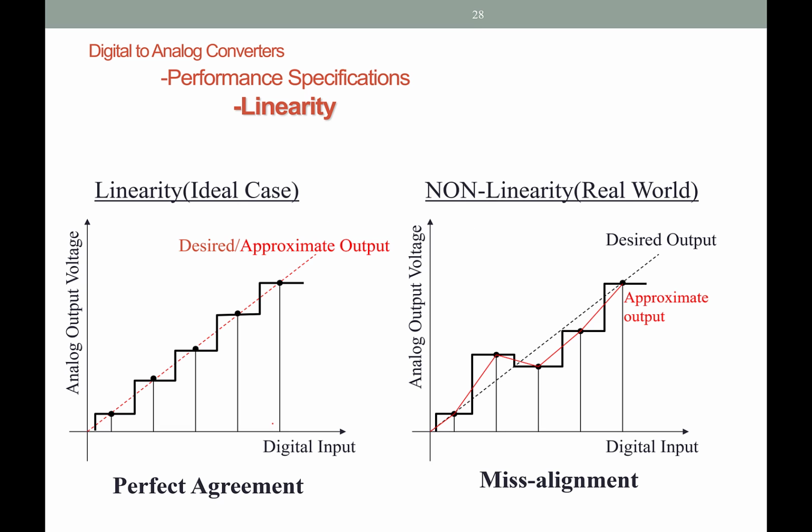So here it's showing perfect agreement with linearity, and you see this straight line going through, saying each particular binary level that you have, so this level, this level, this level, has the same separation to it. If you don't have that case, then you can have some particular problem, and you can see here's this misalignment.